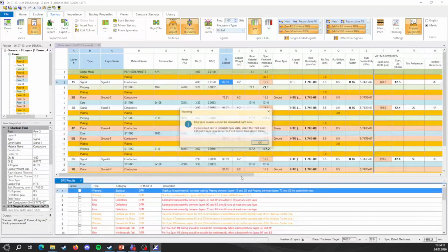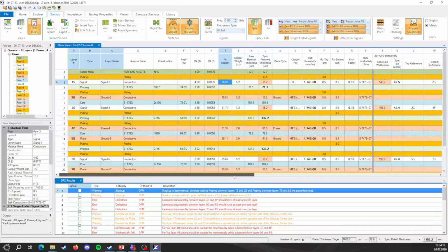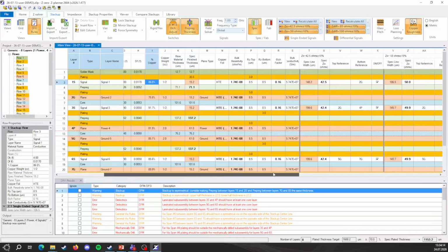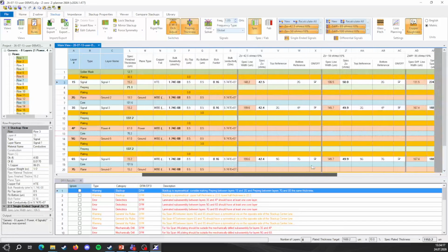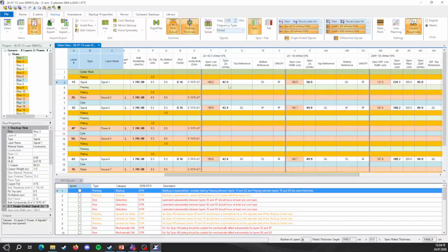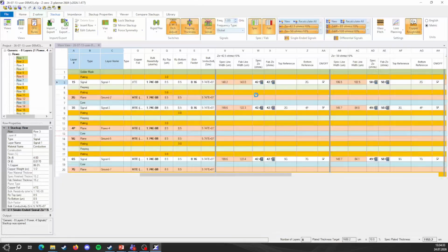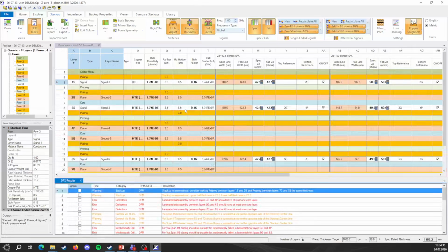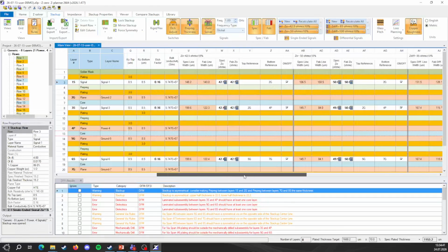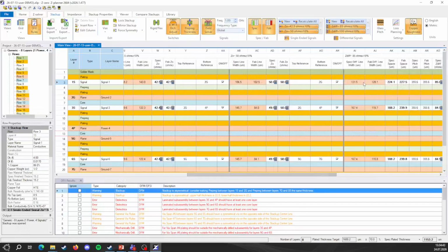Let me disable fabrication. And if we take a look at impedance profiles, we will see that in specification it should be 42.5 ohms on the top layer or 50 depending on net. If I enable fabrication, first of all, it will change the thicknesses of prepregs. Second, it will recalculate our effective impedances.